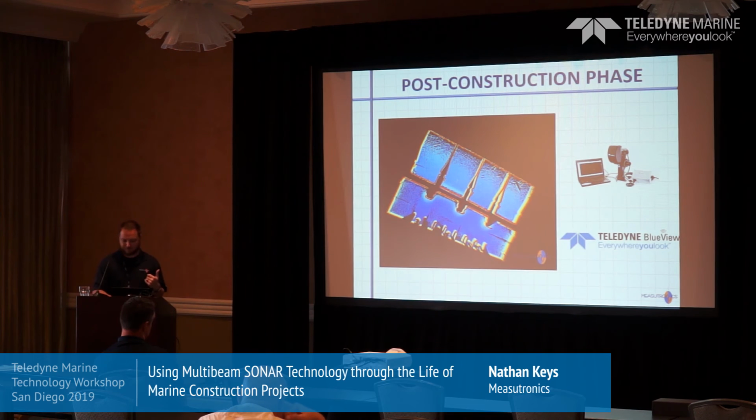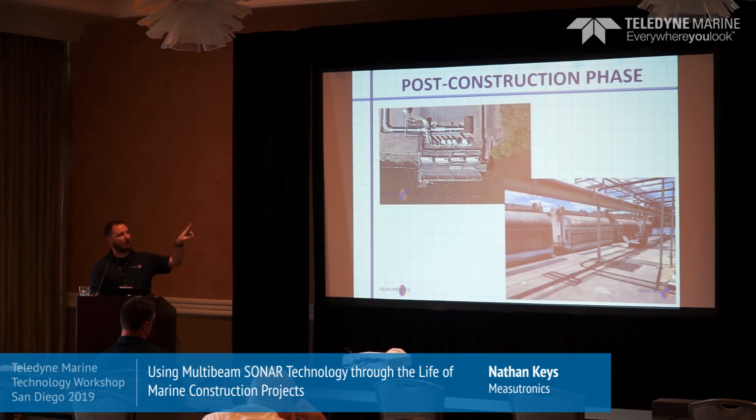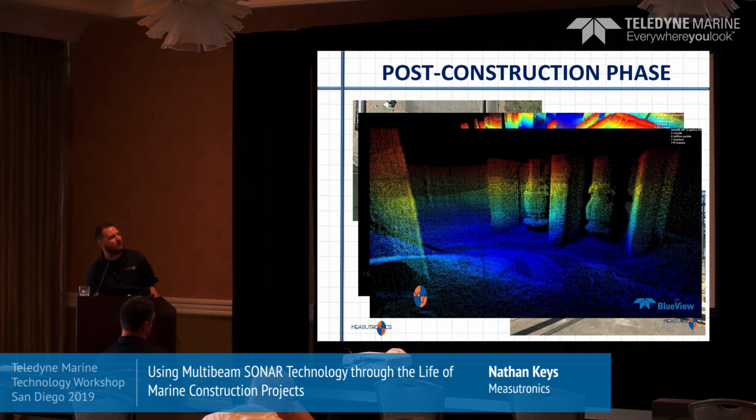On the upper left there, that's just a Google Earth image of the intake. So Columbia River's below it, and that's just a picture. You can see some grates there on the ground. That's where we dropped the sonar through those grates on a big long pole. And we did a bunch of scans, and here's just another view from the scan. You can see there's some logs, and you can see the ladder there. And again, the BlueView, if you stay within the range requirements, you can get some really good data.